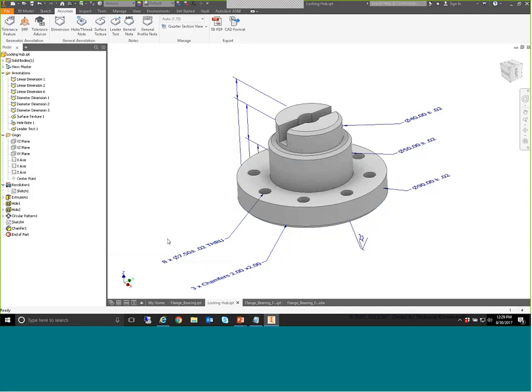And I can select OK, and you can see how that is a note that now is an annotation added in my model indicating the chamfer sizes. So unlike that hole thread where I couldn't incorporate a parameter, I was able to incorporate a parameter into leader text. And finally, general notes, and these were ones that I mentioned lie on the graphics plane.